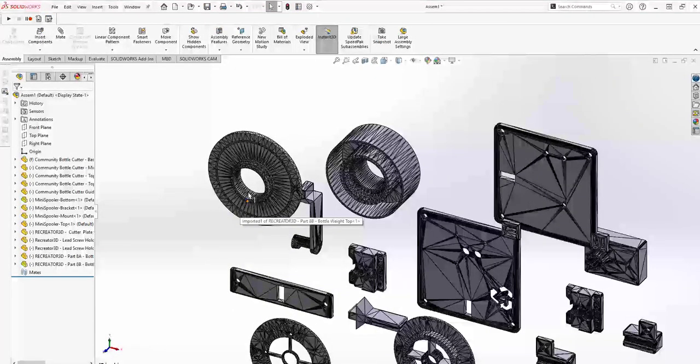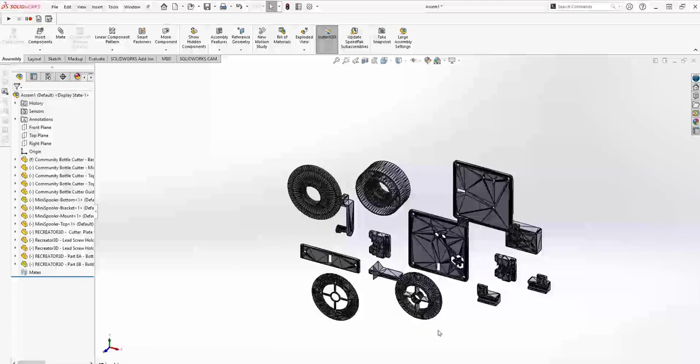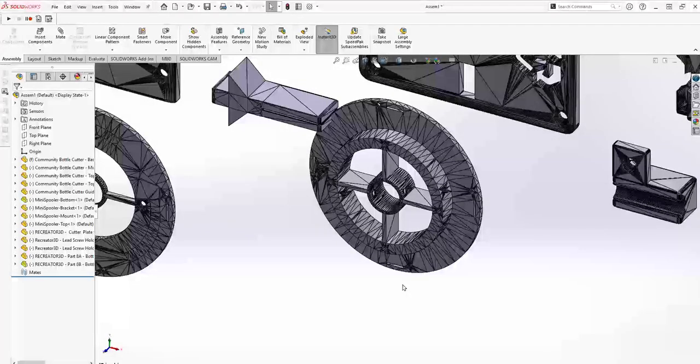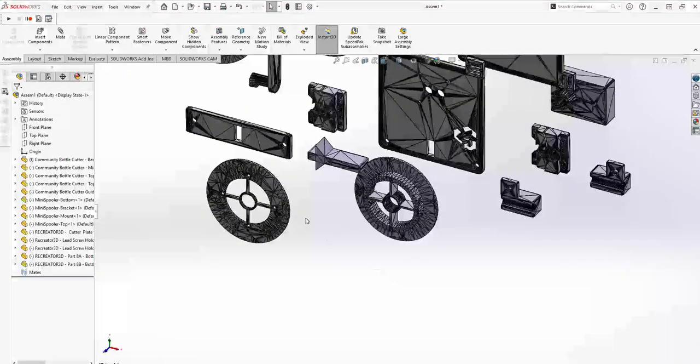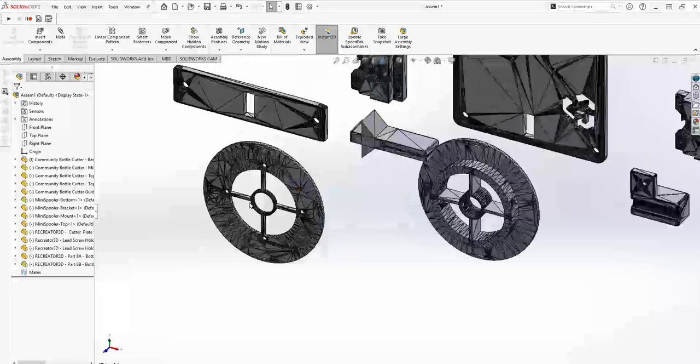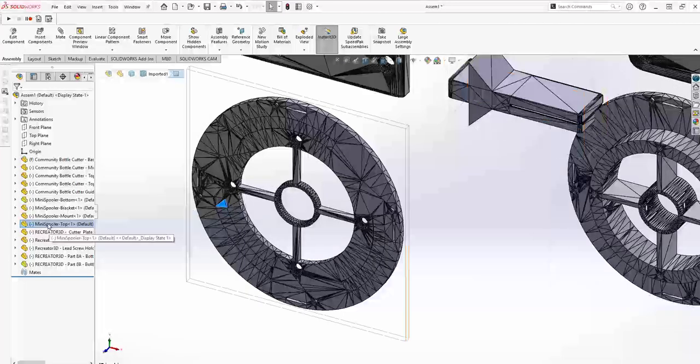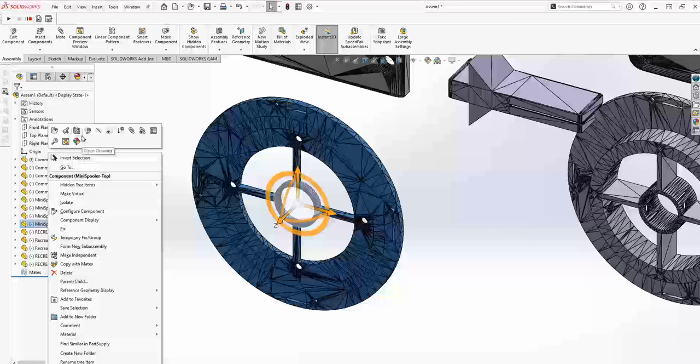And now I have started a new assembly, imported all the components that I want to assemble. But here, for example, if I want to make that hole, that part, have this cylindrical face concentric with the other one, that is not immediately doable. So what we can do here is we just pick what features are essential for that assembly. So first thing, I go and select this part, and then I go to edit the part.